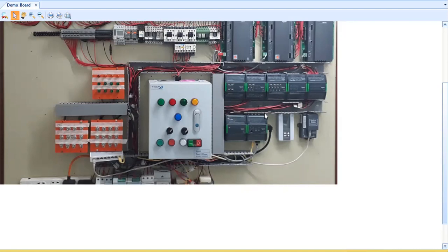First question: how does a DDC controller communicate to other DDC? So again, from my automation server, I will be connecting a BACnet MSTP network so that my BACnet controllers can communicate to my automation server. Then this automation server will be connected to a network switch using a Cat6 cable.